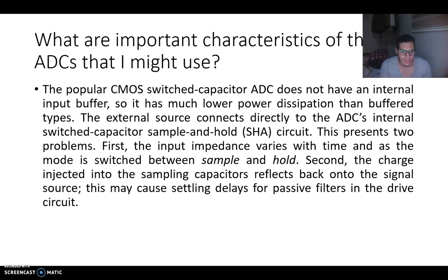This presents two problems. First, the input impedance varies with time and as the mode is switched between sample and hold. Second, the charge injected into the sampling capacitors reflects back onto the signal source. This might cause settling delays for the passive filters in the drive circuit.